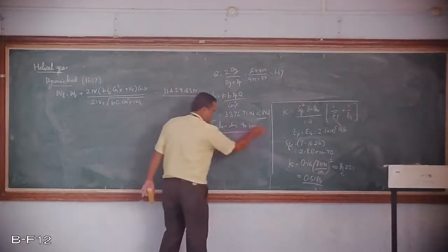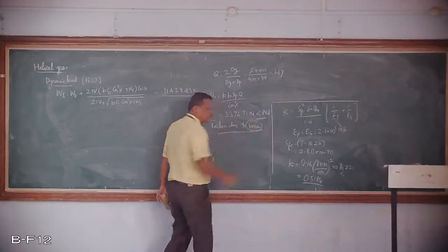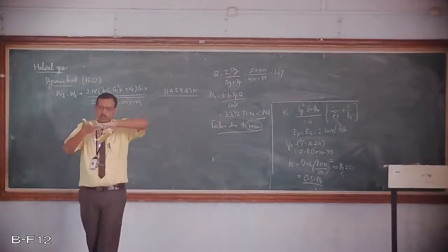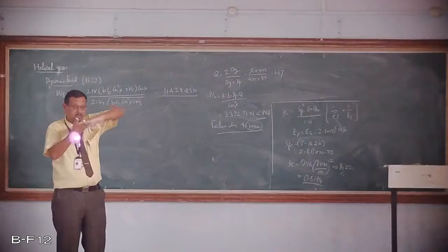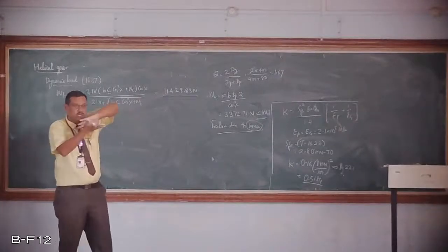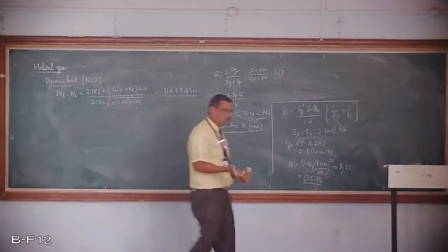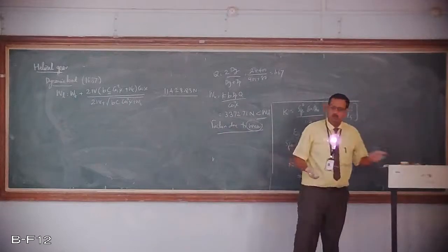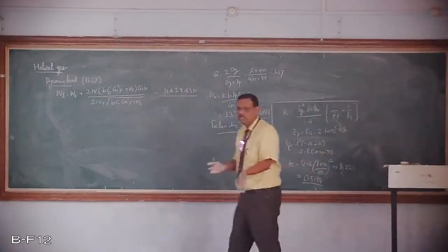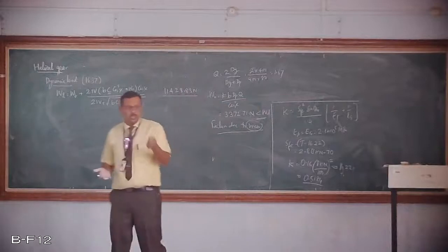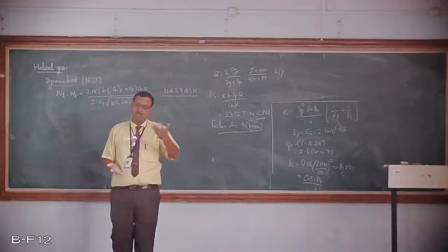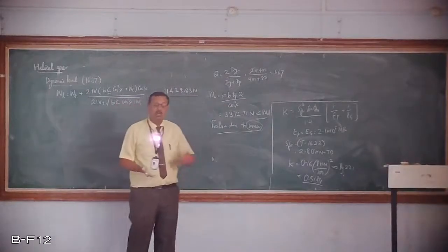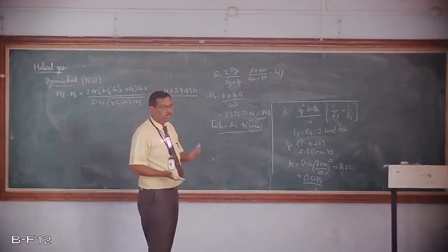When you are talking of wear, it is due to the relative motion between the two teeth. There is rubbing. One tooth is going to slide over the other. Though there is some lubrication, there will be a slight amount of wear and tear. If you increase the hardness of the teeth, naturally the higher the hardness, the less the wear, that is, the more the wear resistance. Therefore, you have to increase the hardness.